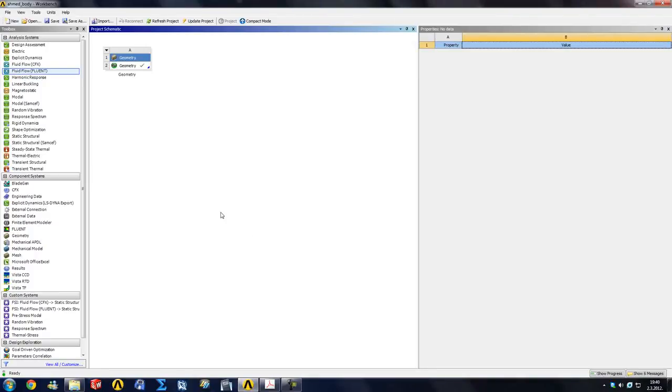Okay, so we ended the last video with me telling you to keep everything in the same folder, all the way from your original geometry files, which are imported into Workbench, and all the way to the simulation results and stuff like that. The reason for this is so that when you're done with your simulation, you can zip the folder up or move it to another hard drive or back it up to a DVD or something like that. And when you put it back on your hard drive and open up the project, everything will be in place.